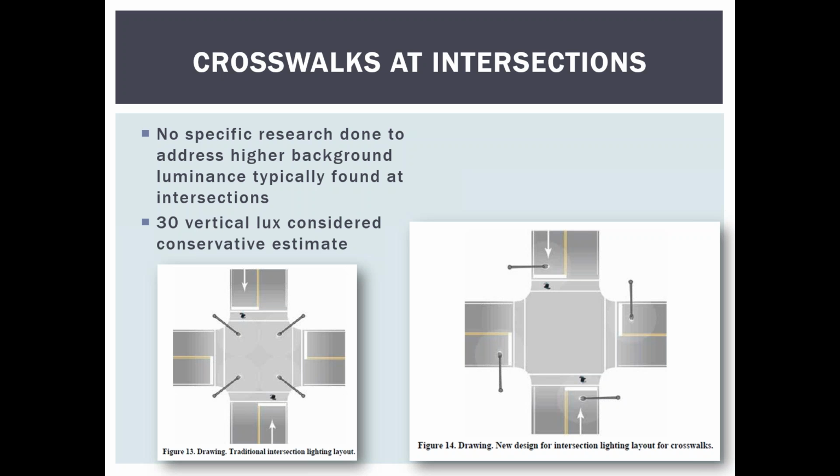But you're talking about the case where there are turning cars. Turning cars are going much slower than the high-speed cars that may be approaching it. So I think it's more important to do that. Plus, when you get wider intersections, I wouldn't be surprised to see 8 lights illuminating the intersection, having lights coming on both sides, so that you have a more even light distribution. These are very simplistic, small intersection designs.